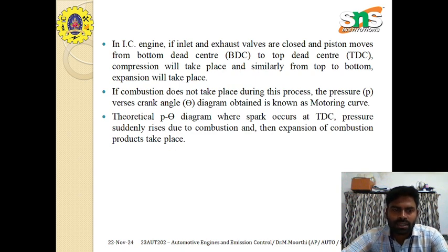During the suction stroke, the air fuel mixture is fed into the combustion chamber, where the piston moves from top dead center to bottom dead center, and during the compression stroke the piston moves from bottom dead center to top dead center. Here the air fuel mixture is compressed, so it attains higher temperature and pressure. After the compression stroke, the piston moves from top dead center to bottom dead center, so that the expansion stroke takes place. So these are the various strokes happening in the spark ignition engine.